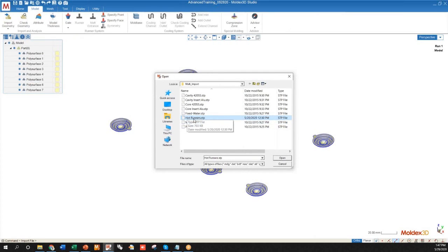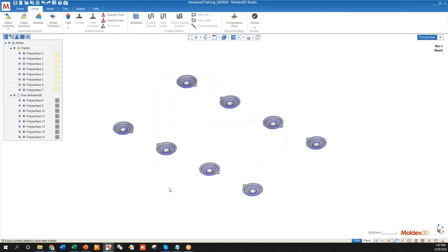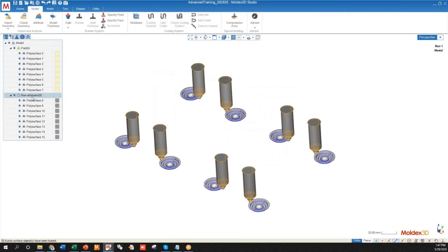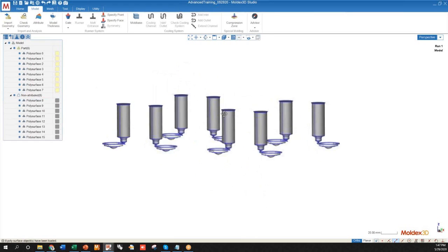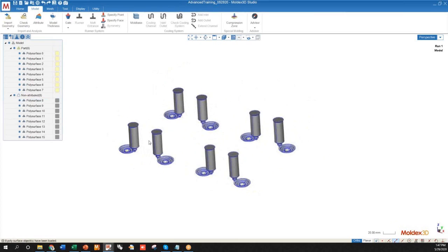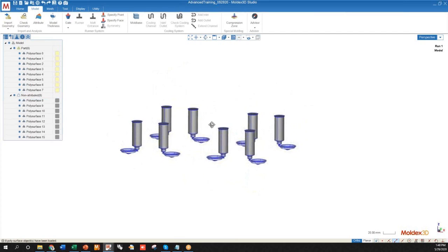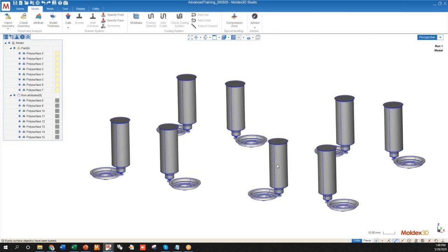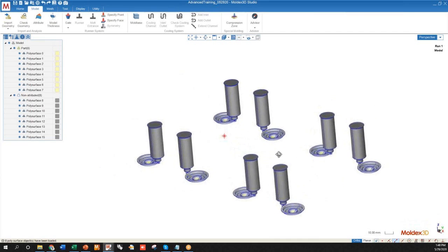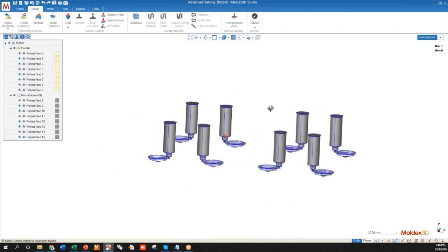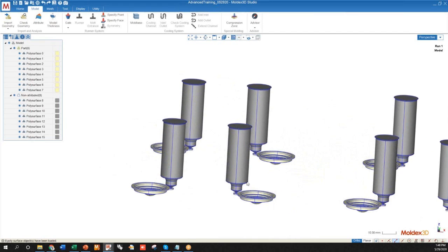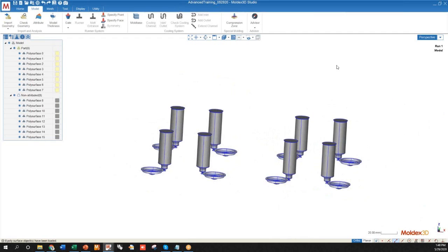So I'm going to bring in the second component here of my melt system, which is going to be the hot runners. I've only brought the hot runners up to the top of the drops, really. I didn't bring them all the way up to the sprue. And we'll see that in just a moment. We see that they're just kind of a big blocky object. And most of the time, whenever you're modeling a hot runner system, you will almost always want this runner system to be complete. You won't want any sort of simplifications like this. I just simplified this to make it a little bit easier for us to go through the process. But in all realistic scenarios, you would definitely want these drops to be connected into one system.